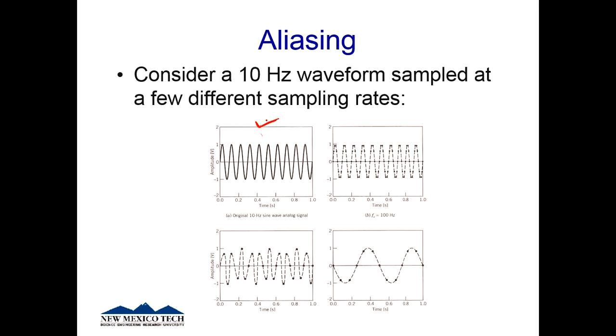It applies no matter what you're doing. So if you have some temperature signal that looks something like that, doesn't matter. For this demonstration, I'm just putting in a 10 hertz signal just to show what happens. But this aliasing effect comes up no matter what you're doing. So anyway, there's what reality looks like. It's a 10 hertz signal.